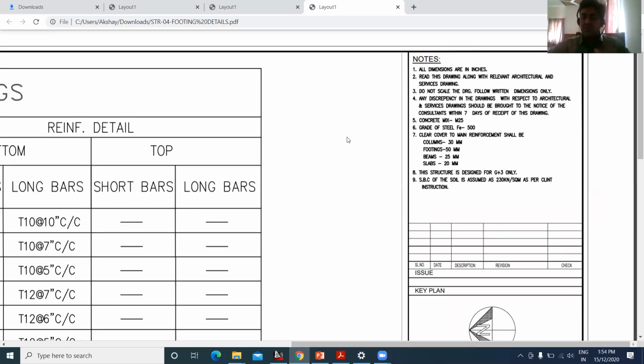If you observe the rebar very carefully, you have different diameters of the bar, like 8 mm bar, 10 mm bar, 12 mm bar, and then 16, 20, 25, 32, 36. These are the common diameters of the bar that is available in India. In US or in some other countries, this diameter may vary. In some countries 14 bar is also available, 22 bar is also available, 28 bar is also available. So based on the bar, we can do all these designs.